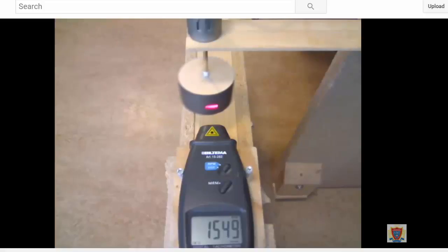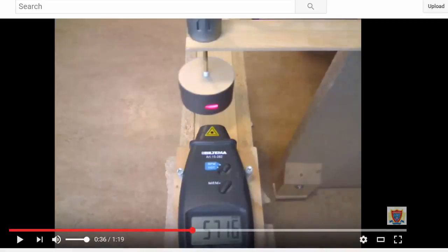And then every time we hit an integer multiple of that natural frequency, the second natural frequency, the third natural frequency, it will do those vibrations again. When you hit that natural frequency, it causes that high excessive vibration that we saw before. I'll come back one more time. There it is.